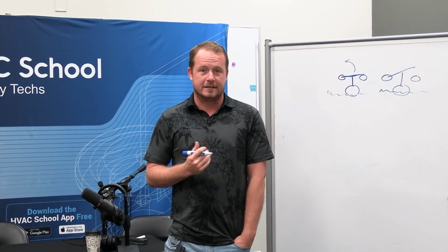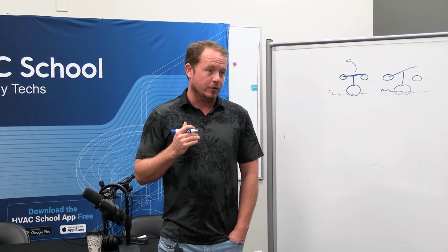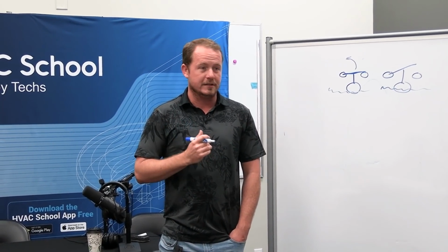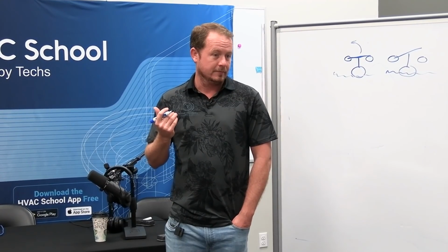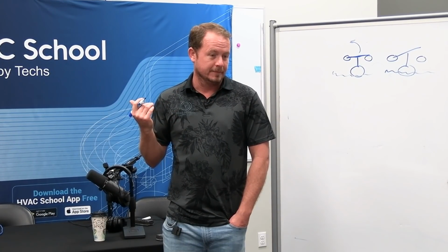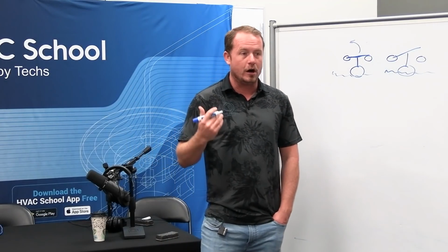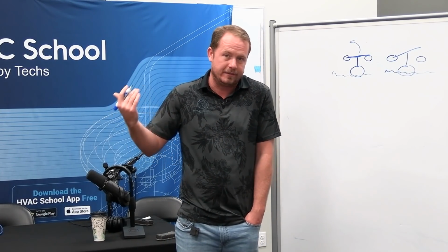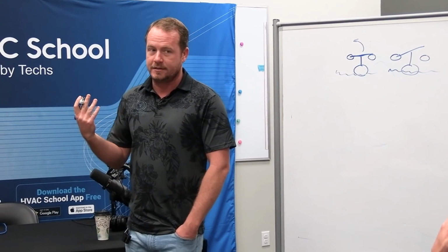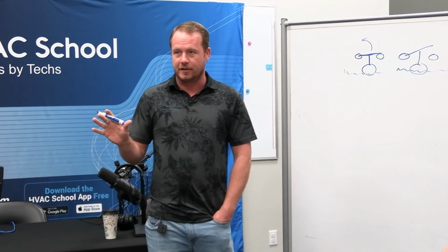If you walk up to a system and it has an open float switch, you wouldn't just say, oh, it's a bad switch, replace the switch. Would you? What would you do? Check to see if there's water. You check to see if there's water in it, right? So you'd first see, is there an active cause? Why is it open? That'd be the first question. The assumption would be it's open because there's water in the float. That's what it's there to do. That's fairly obvious.